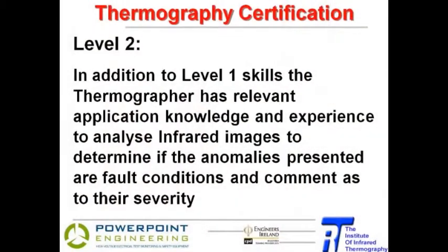And then we talk about level 2. In addition to the same skills that a level 1 thermographer will have, they're going to mentor a level 1 thermographer, but they're also going to have application knowledge and experience. Because now you're talking about analysing those images and determining whether or not it is a fault condition. Often we can look at images and we're explaining it away. We can see an anomaly, but there's a reason for it, and so it's not a fault condition. And also you might be expected to comment as to the severity. So again, if you're doing electrical surveying, does it need immediate attention? Or can we wait for the next planned shutdown?